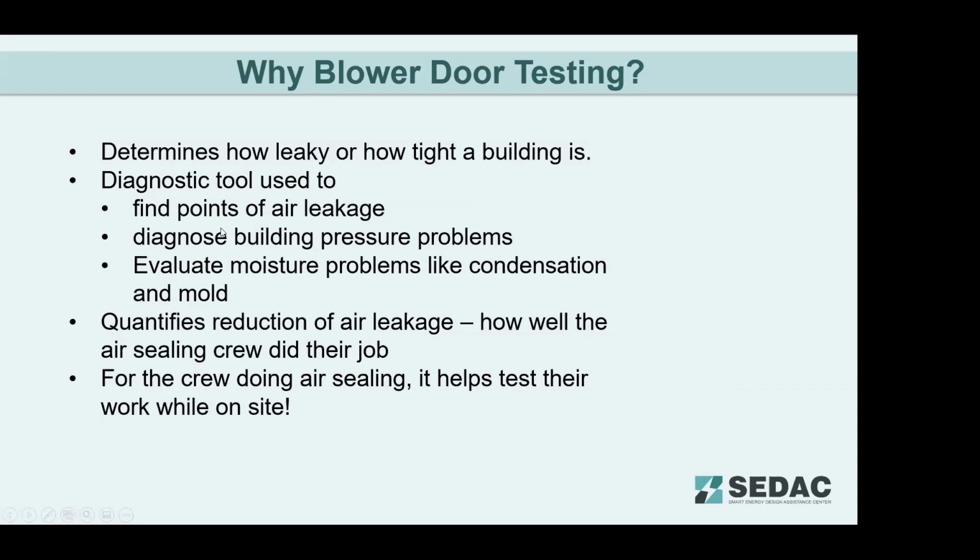So why are we doing blower door testing? Sean mentioned this a little bit earlier, but it's going to determine how tight or how leaky the building is. It's going to give us an overall leakage rate. But beyond that, it's also a diagnostic tool. And whether we're doing new construction or existing buildings, we can use the running of the fan to walk the house and to figure out where points of air leakage are in the house. We can also use the blower door to diagnose building pressure problems, to evaluate moisture problems like condensation and mold.